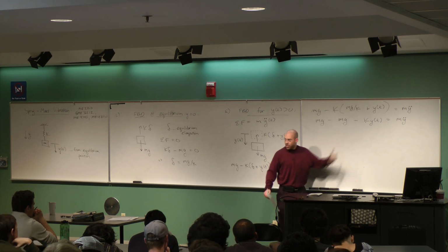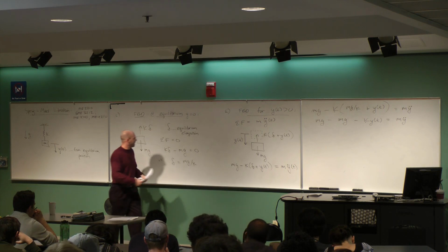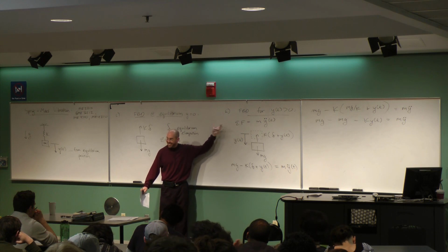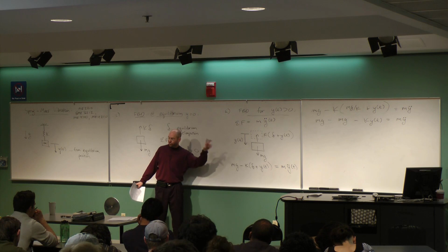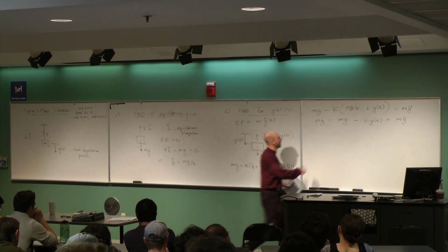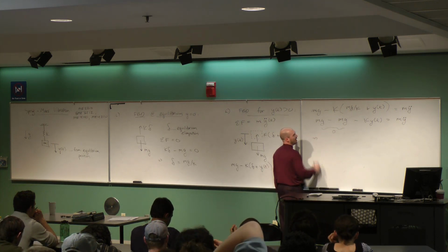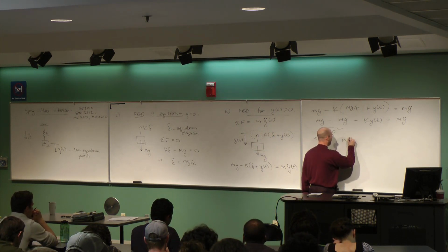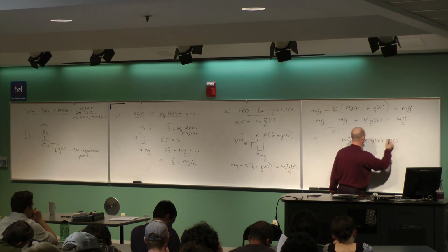That's because of how we defined it. The weight is not in the equation because we defined equilibrium to be at the elongation. So the equilibrium elongation is the starting point. We took care of the weight by doing that, and that's the reason it cancels out. So this is 0. And so what's the net result? If I put all this on one side of an equation, I get m y double dot plus k y of t is equal to 0.